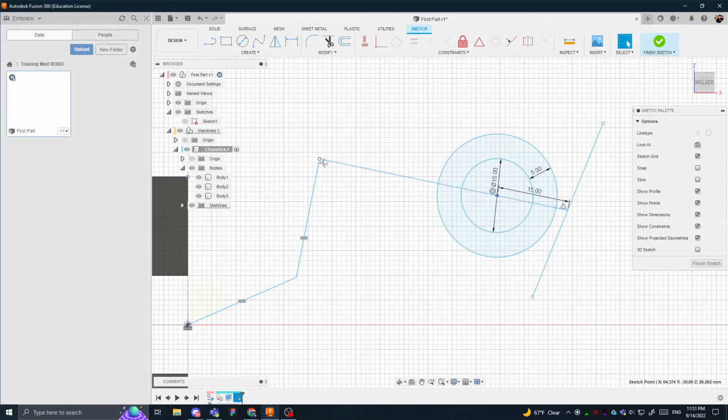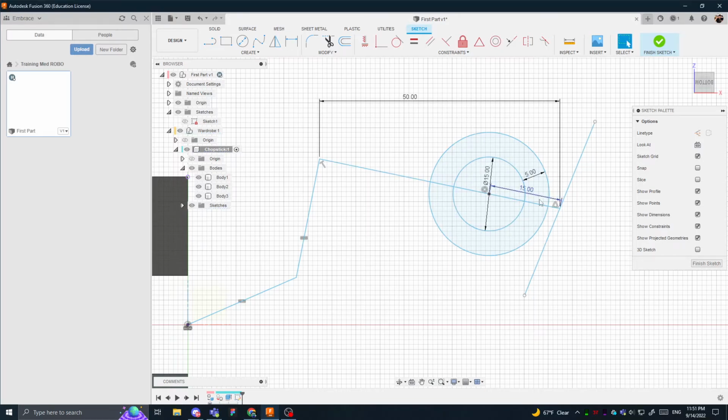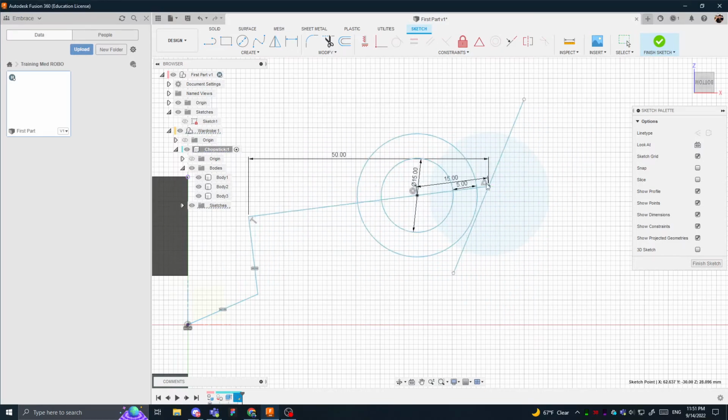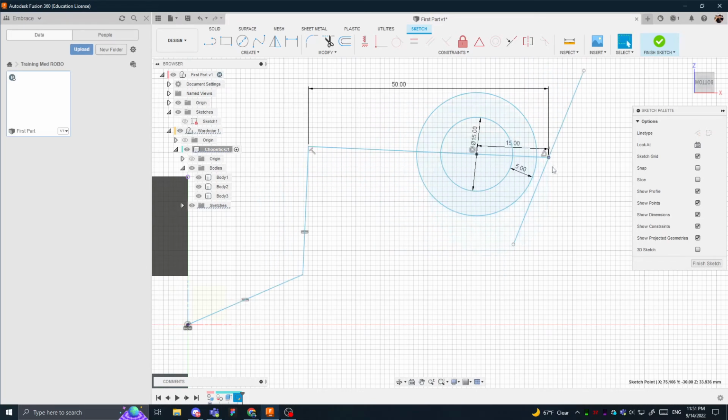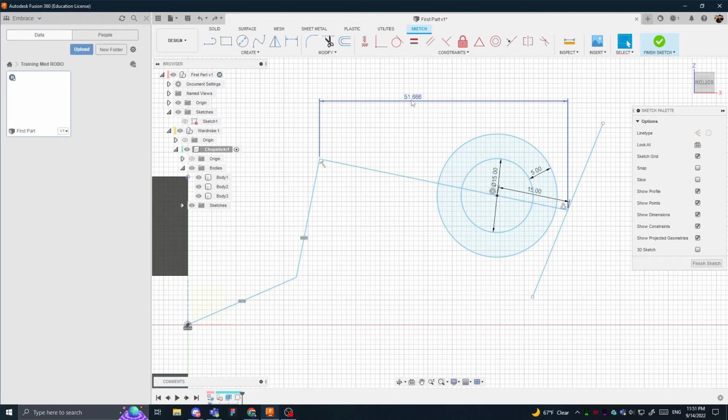This is moving because it can still stretch along this line, so we'll limit this line's motion, and I don't want it like this or else it can possibly rotate. If I just type a number, I think I should be able to make it an angle. So you see it stays that length, however it changes angle, which is not what I wanted. So I'm just going to delete this and make a new constraint.